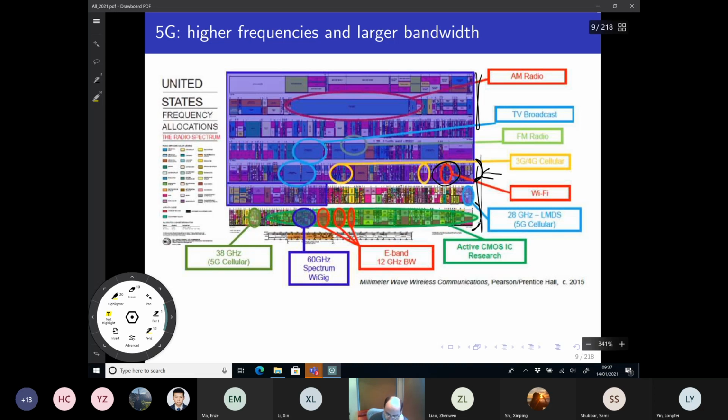And so this is what you have here, for instance, in the 28 gigahertz and higher, where the wavelength is much smaller, but the propagation loss can also be quite significant. So in 5G, you have typically an operation below 6 gigahertz that will enable you to have very good performance over relatively large coverage. And then you have the much higher frequency bands, the 28, 38, 60, and so on, which lead to severe propagation loss, and so the coverage or the cell size would have to be essentially smaller.